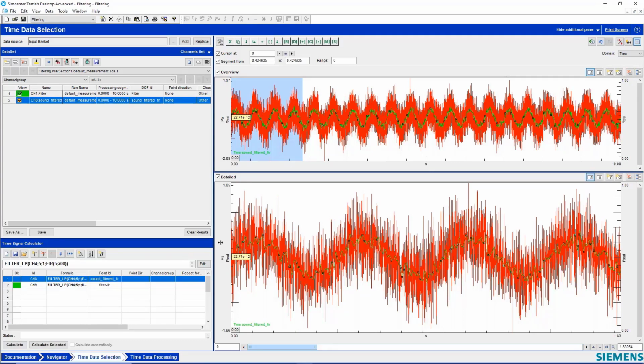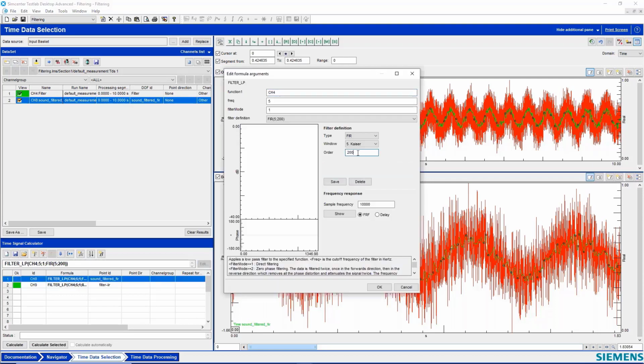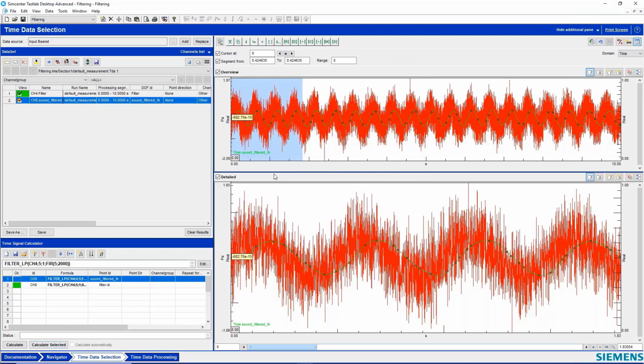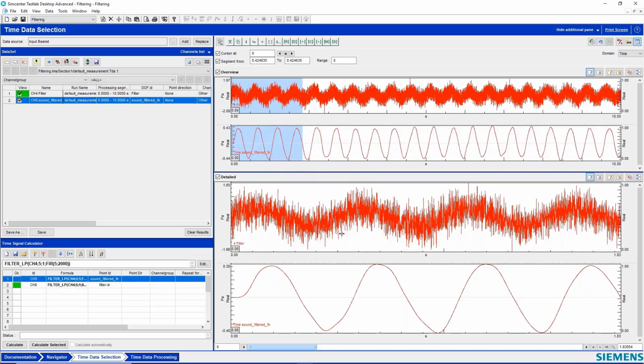Yeah, now we can move the ball a lot. I could even go up by another factor of 10 here. Show that. And that's even sharper than it was when it was 200. So with 200, it looked like that. With 2,000 as my order, getting there. I'll hit calculate. Whoa, it looks like I managed to retrieve that sine wave pretty nicely by changing the order. And you can see the original one was minus 0.4 to 0.4. So we're actually getting pretty close there.